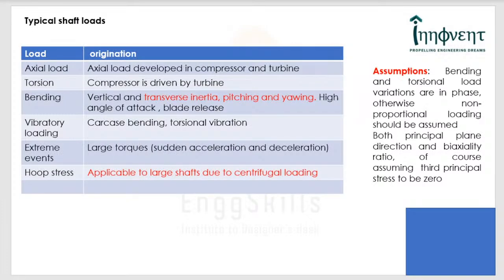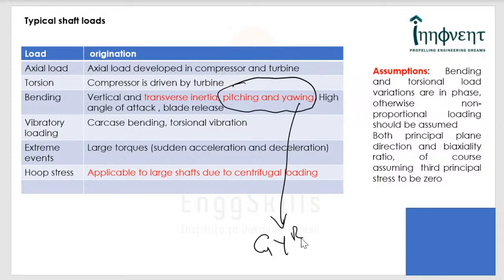Now let's look at one of the interesting hand calculations. In the beginning, several loads are very important. When I was discussing a bearing support structure, you might remember that I spoke about these maneuvers, pitching and yawing of the aircraft, which can bring about a huge amount of gyro loading. And of course, we also spoke about inertial loading and thrust loading. One of the loads that we want to consider here is the centrifugal load.